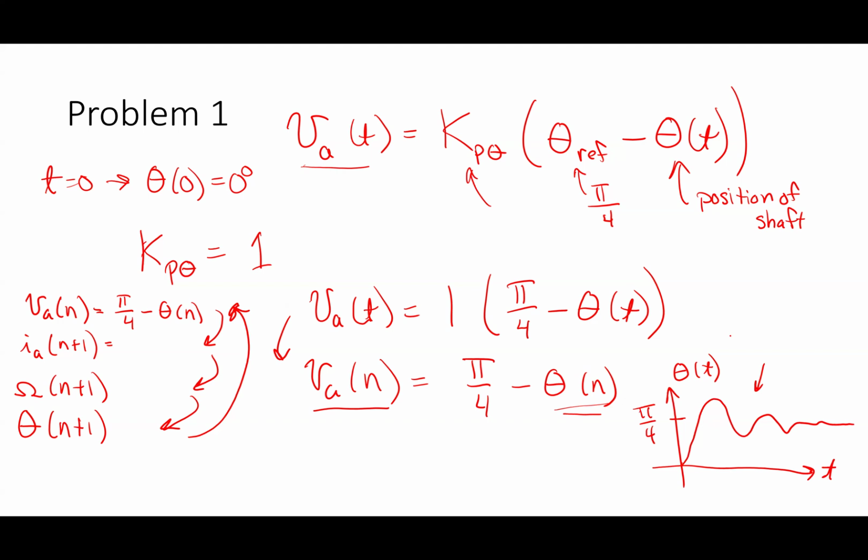Because again, we talked about this before. If I'm controlling something like this, it would mean that if I was looking at the motor, you would see it spin towards 45 degrees. So it would spin past 45 degrees, overshoot it a little bit, and then it would go less than 45 and then more than 45, and eventually it would settle in at exactly 45 degrees. It's not a particularly hard problem if you can understand what's going on here.